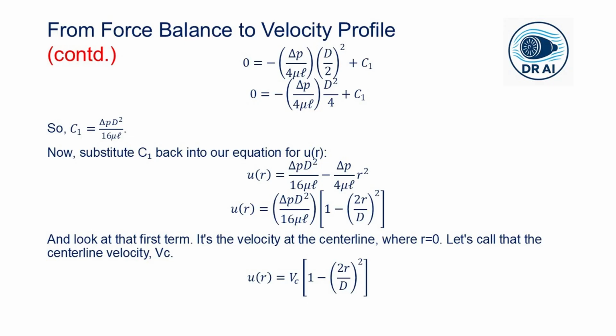So this is it. This is the exact velocity profile for fully developed laminar flow in a pipe. It's a paraboloid. It's zero at the walls, maximum at the center, and beautifully smooth. This flow is so important, it has a name, Hagen-Poiseuille flow, after the two scientists who first described it experimentally in the 1830s and 40s.